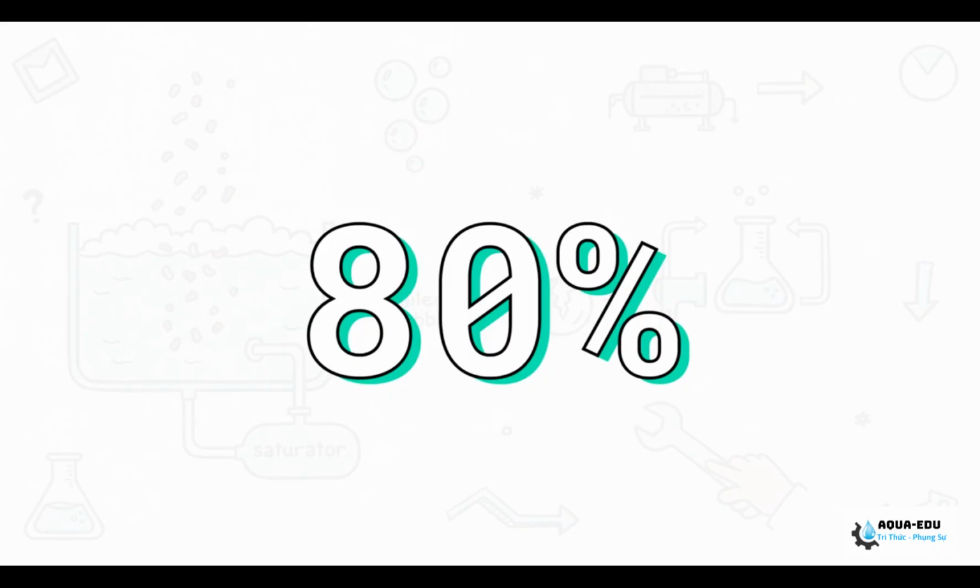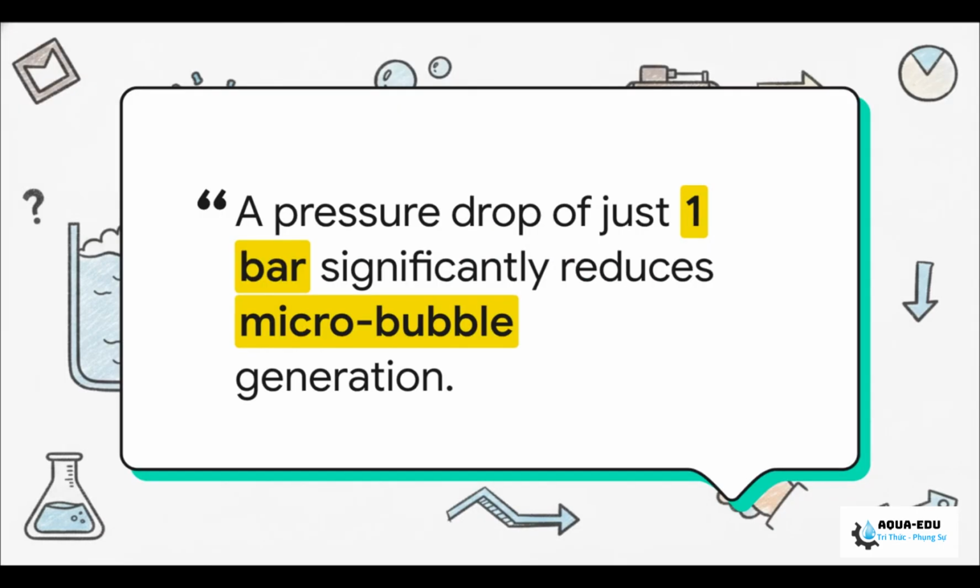Well, we know the fix is completely successful when your pressure holds rock steady for a week, your bubbles are uniform across the entire tank with absolutely no dead zones, and your total suspended solids at the output are reduced by at least 80% compared to the input. When you see that magic 80% reduction, you know your DAF is back online protecting those biological tanks exactly like it should.